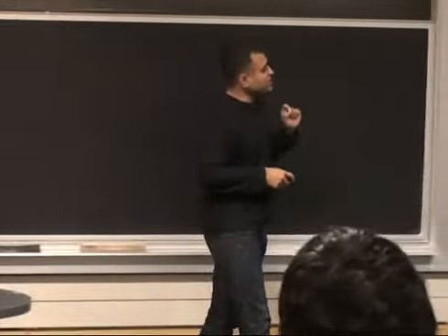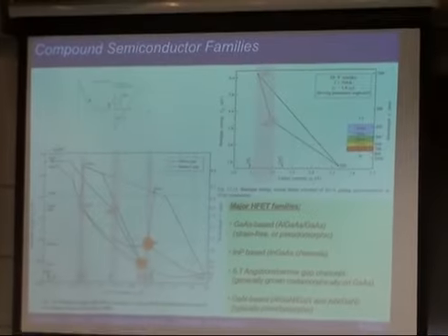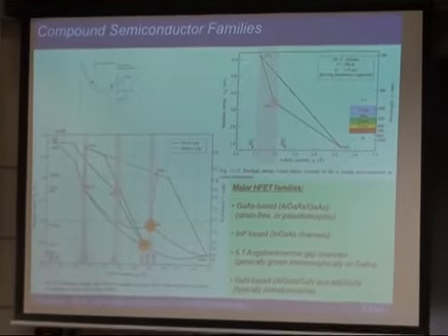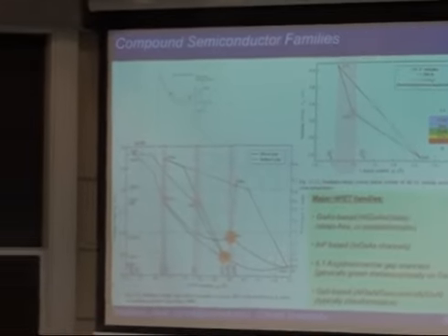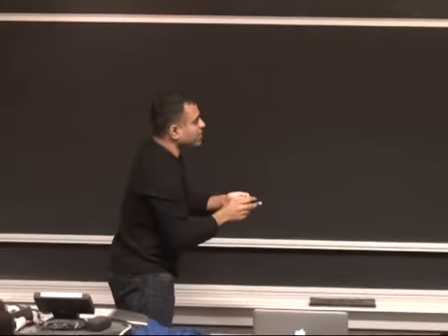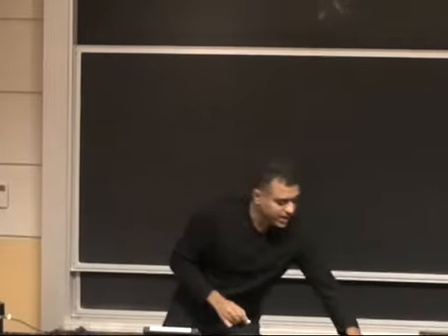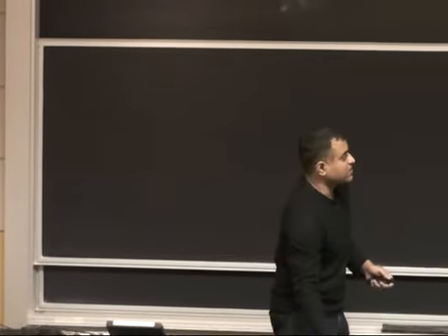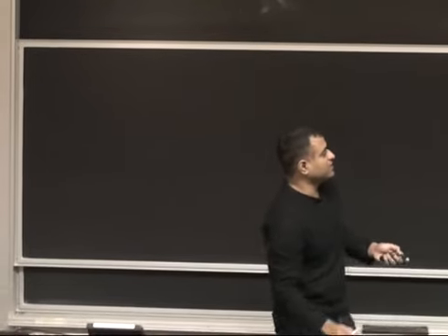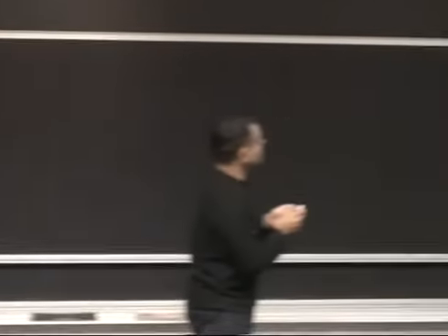So today what we're going to do is look into some of the more details of if I'm able to create, for example, a compound semiconductor heterostructure, which has, let's say I choose a wide bandgap aluminum gallium arsenide or something like that here, and I know its bandgap, going back to the bandgap versus lattice constant picture that we had developed. So for simplicity, let's assume that we have a heterostructure between aluminum arsenide, which is here, and gallium arsenide, which is here.